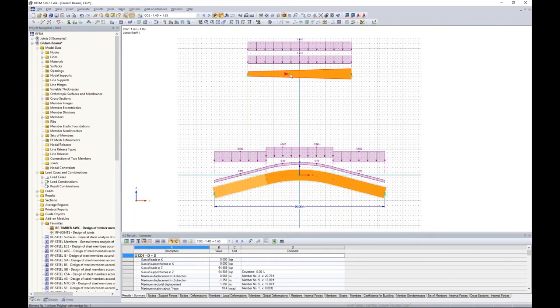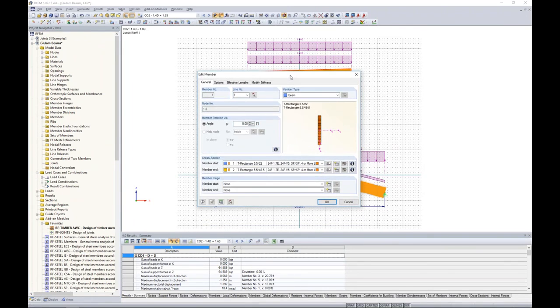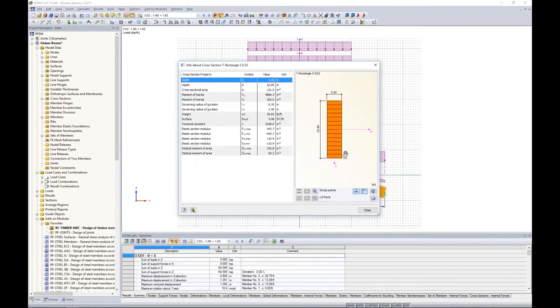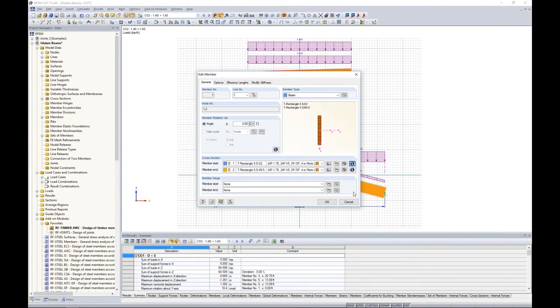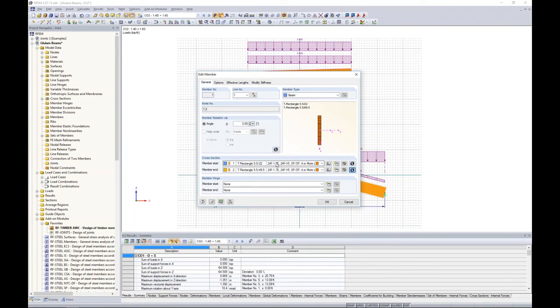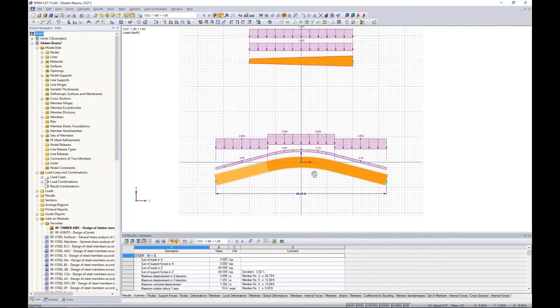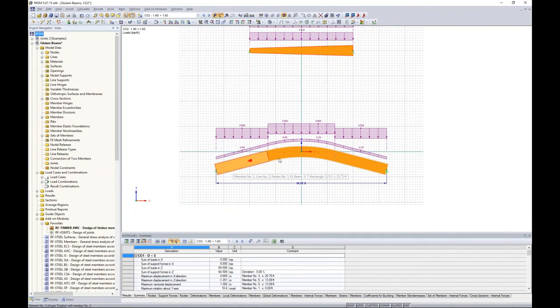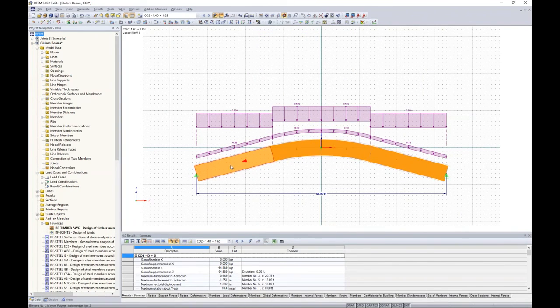Well, you can see that our first member here is just a simple tapered member, and how we define a taper is 2 different cross sections at the start and at the end. A pretty deep member we're looking at here, 22 inches in depth for the start, and at the end we have a depth of 49.5 inches. Again, it's assigned as a glulam material, so the program automatically recognizes that. As far as the curved member, these are 4 different beam elements. So again, I created a set of members so I can do design for this entire beam as a whole rather than each individual member.